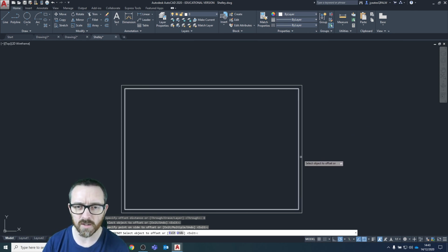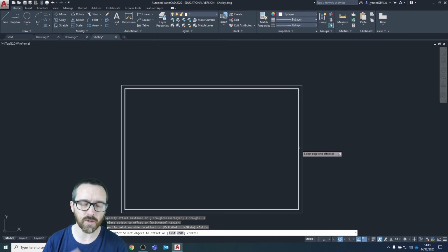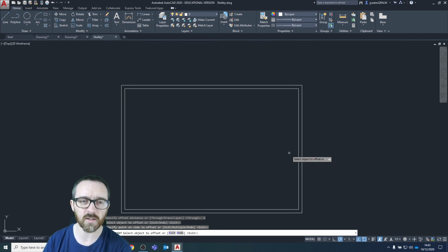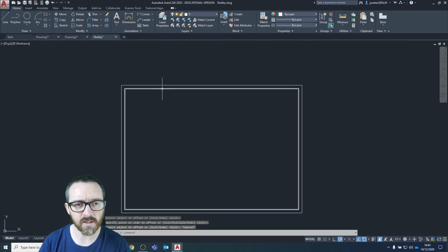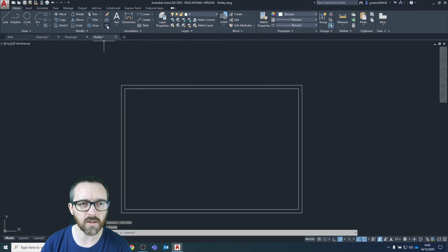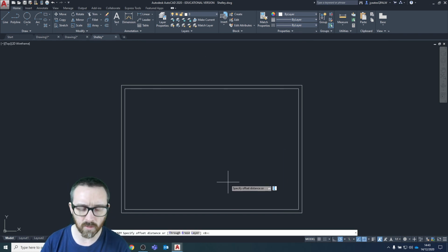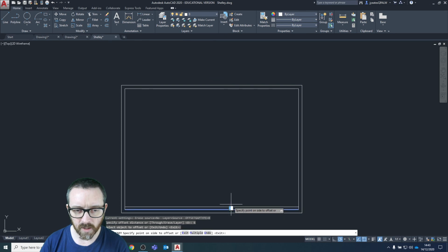So we've got this line around the edge that we will see. We won't see the outer line because it's the edge of the paper, but we should see this line when we print, and that's going to reassure us that everything is to scale and everything's correct. Nothing has been scaled to fit or anything like that. Okay, now I'm going to press escape, select this line and type in explode. I'm going to explode this rectangle, because I need to offset some lines. So I'm going to offset the lines from the bottom edge 6mm. I'm going to offset here, here, and one more.